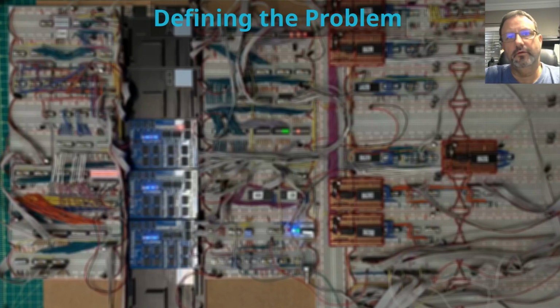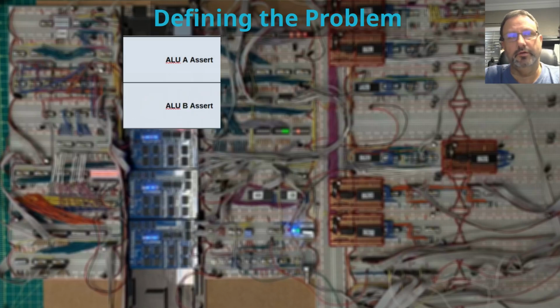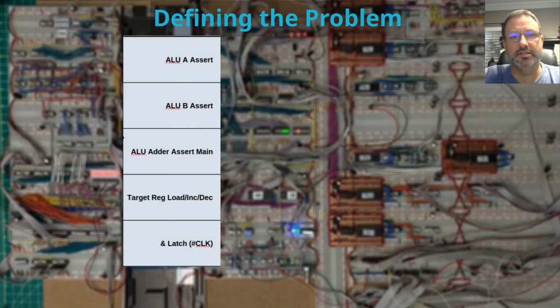All right, for the ALU adder, there are 5 signals that need to be coordinated and worked out timing-wise. At least that's where we started at the beginning of last video. Those 5 signals are the assert out onto ALU A, the assert out onto ALU B, the assert of the adder results out onto the main bus, the target register load signal, and the end latch signal.